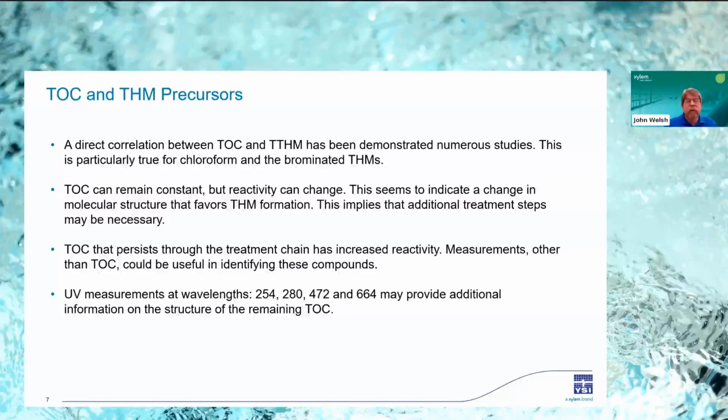UV measurements at wavelength 254, which is very common in many treatment processes. In addition to that, other information could be gleaned at wavelengths of 280, 472, and 664.